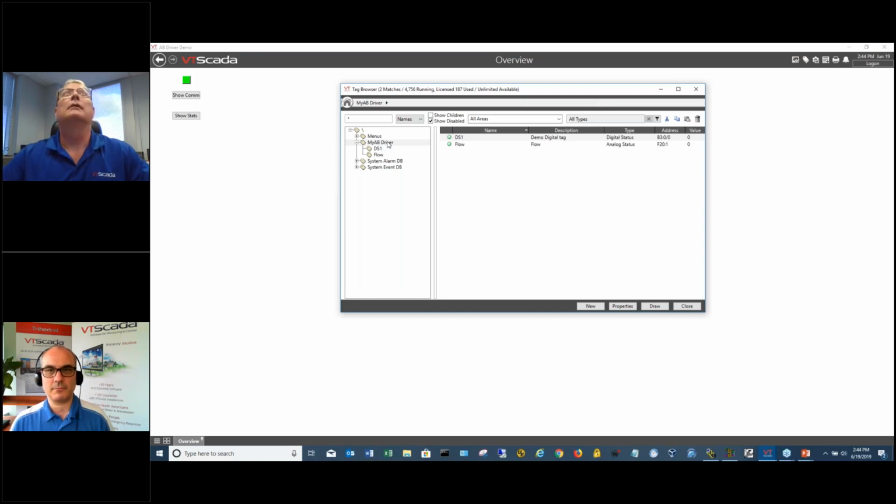All right, so let me think. For every remote device, if you were using Ethernet radios and an Ethernet connection between the radio and the PLC, you can do that with cellular. Most cellular. What about serial? If it's serial, then you've got a serial connection to the master radio. You can use the Ethernet tunneling like I just showed you with my electronics. In that case, you're only going to talk to one radio or one remote site at a time. You'll probably want to set up a poll driver.